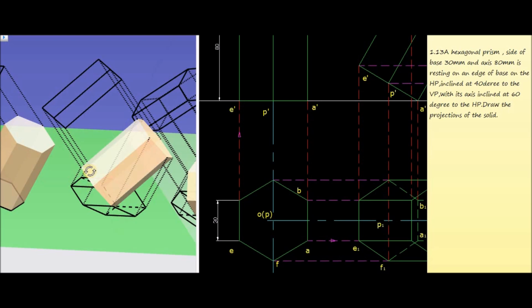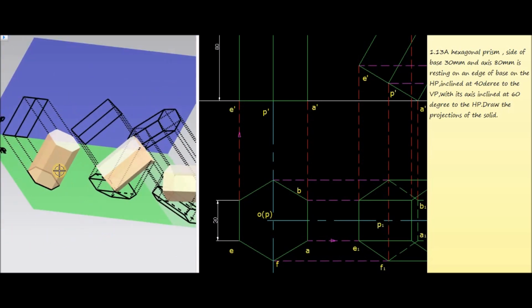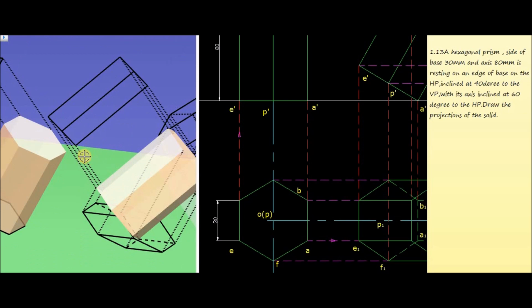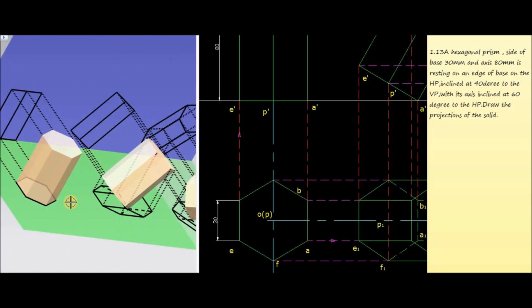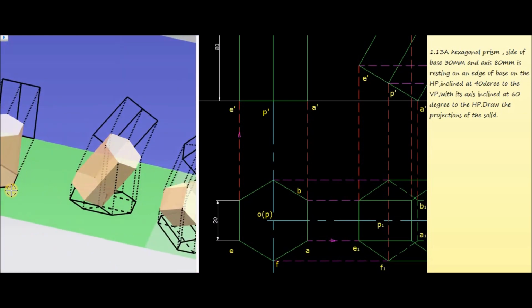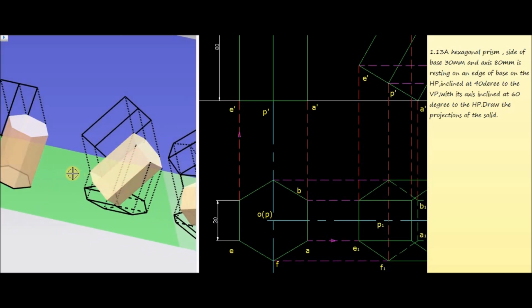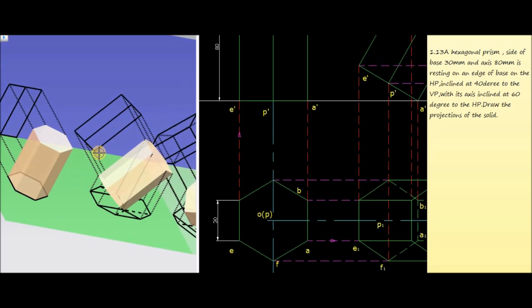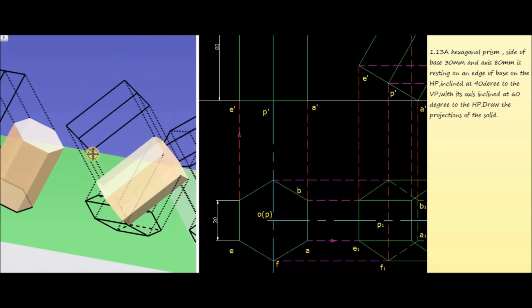So to draw that, from the initial front view take all the dimensions and all the corners, then take this corner, because we are going to tilt the object about the bottom edge AB. Now this will be the line corresponding to the edge AB. Then again this makes 60 degrees to the horizontal plane. Then complete the rectangle like this by taking dimensions from the first front view.